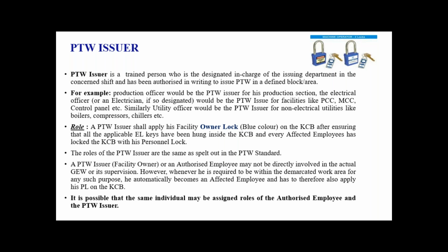Especially when we are not comfortable with some types of work conditions, like where the ventilation is improper or not sufficient, where the illumination or lighting is not sufficient, where the oxygen level is very low or very high, where the diameter of pipelines, manholes, equipments or reactors is restricted, or where the chemical exposure is more. These are the different conditions where the permit to work system should be applied.